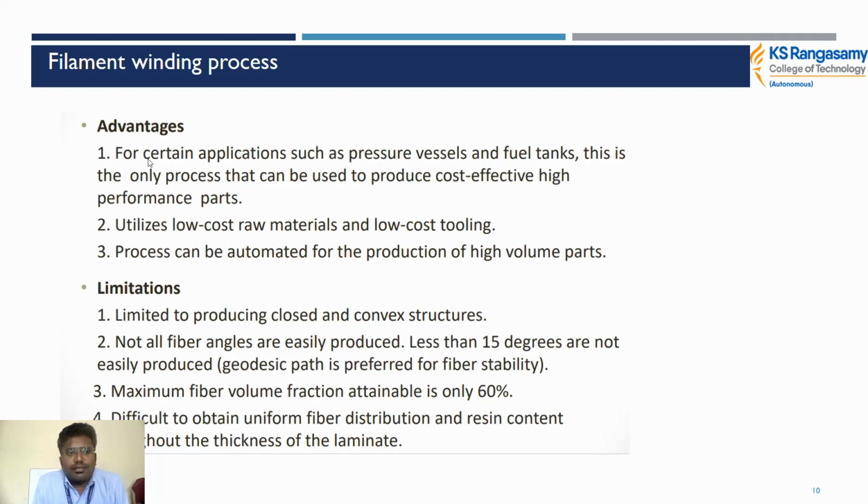Major advantages of the filament winding process are for certain applications such as pressure vessels and fuel tanks. This is the only process that can usually produce cost-effective high performance parts, utilizing low cost raw material and low cost tooling. The process can be automated for production of high volume products.